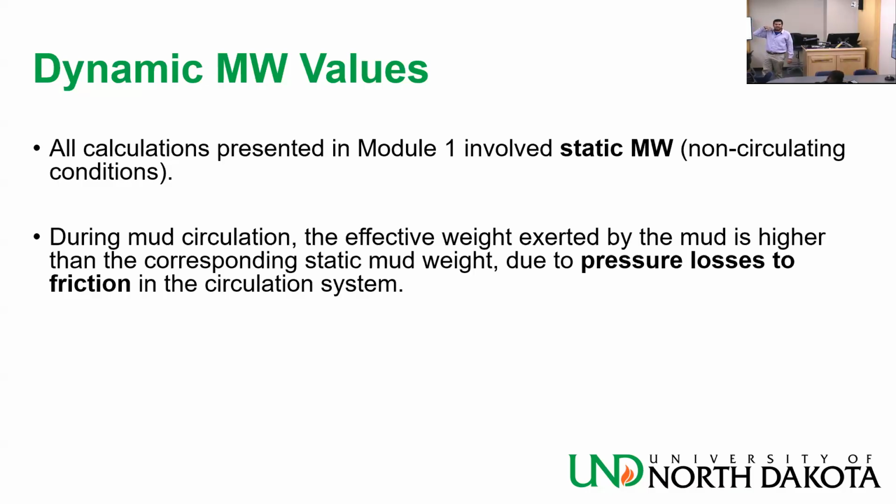So whatever depth I'm going to gain, I'm going to lose eventually. So that's zero, right? But I'm still pumping it at a certain pressure. Say 800 psi: if I'm pumping at 800 psi and I'm getting it out at 0 psi, atmospheric pressure, it means that throughout the system, I'm losing 800 psi to friction.